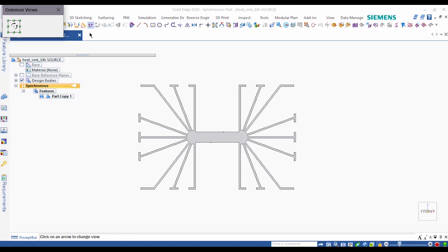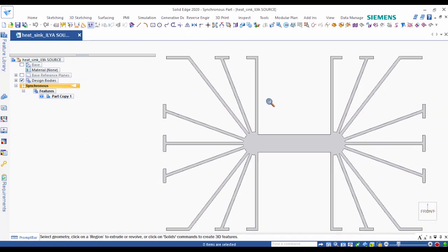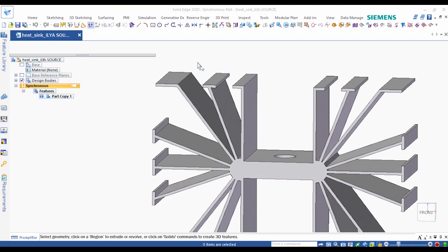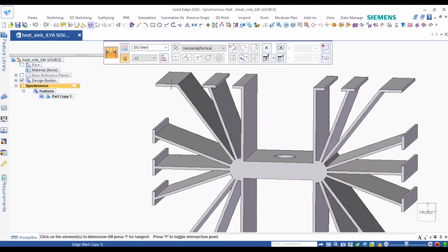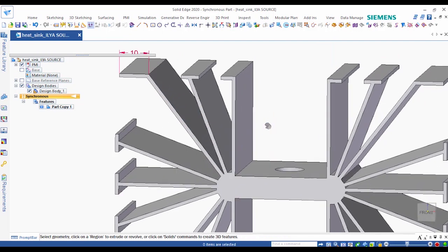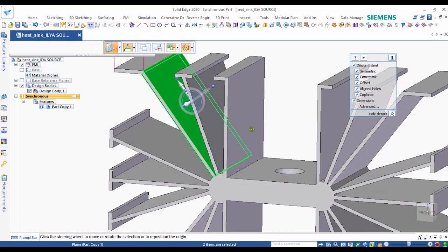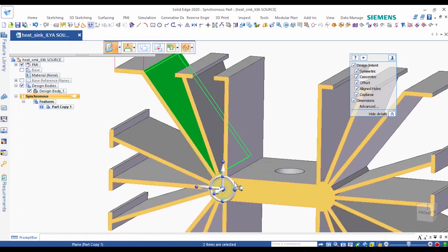Well, okay, so the first thing is to rotate the corner fins 10 degrees to open the spacing of heatsink fins on all four corners. Oh, I see, down by the body the fins are too close to each other. Okay, let's highlight the part of the model that needs to be changed, set the intent rules showing Solid Edge how we want the model to respond during the change, and then take this magnetic handle and place it in the center of our rotation.